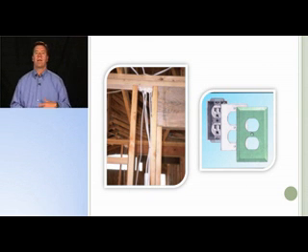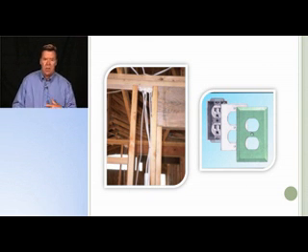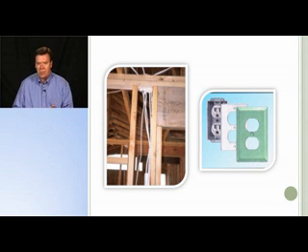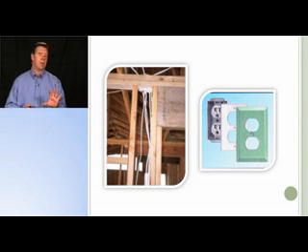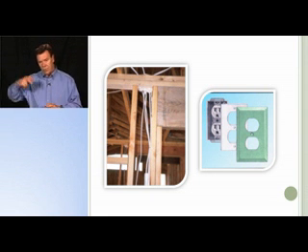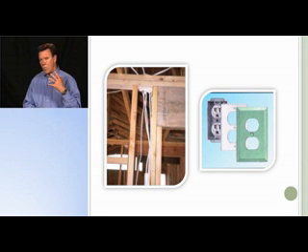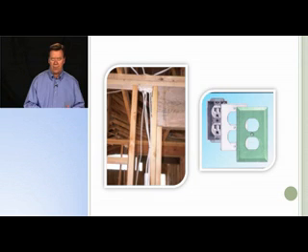One of the things that we do in weatherization programs is that we caulk and seal around penetrations for wires and plumbing. We put gaskets on outlets, anywhere that there could be a potential hole in the envelope, which is our walls and our floors and our ceiling that separates conditioned from non-conditioned spaces. We try to seal those places up so that we can stop that unwanted air infiltration.